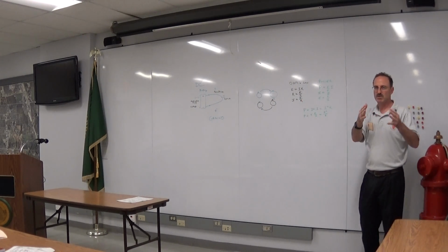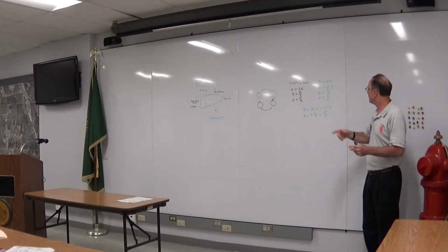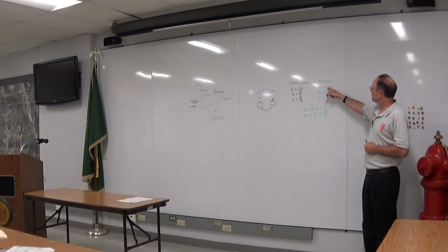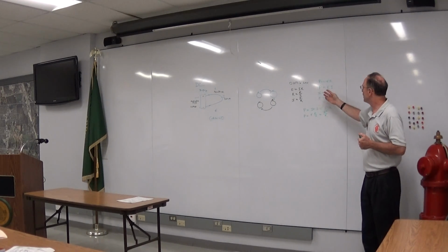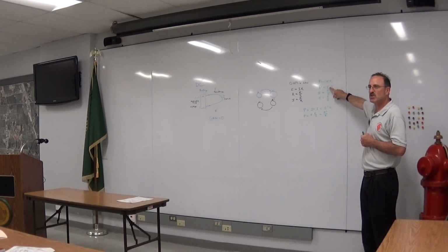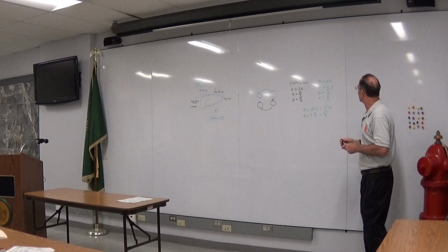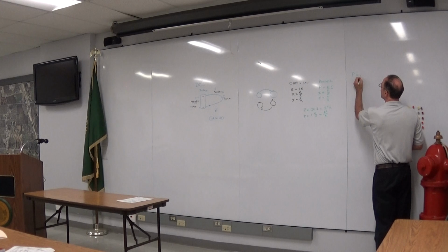Now, at the other end, you're demanding a certain amount of power, EI. So if you want 100 watts, a unit of power, and that power is given to you at 1 volt, that means you're going to have to pull 100 amps.